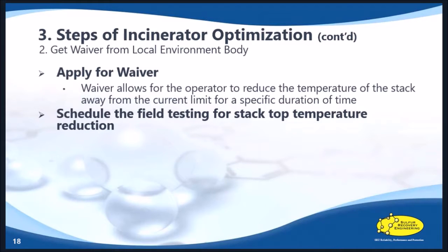Getting a waiver from the local environmental body. In Alberta, it should be noted that an applicant may not proceed with a field study until a temporary waiver of the approved minimum stack gas exit temperature has been obtained from AER. It could apply differently for different locations and plants depending on their local regulatory bodies.